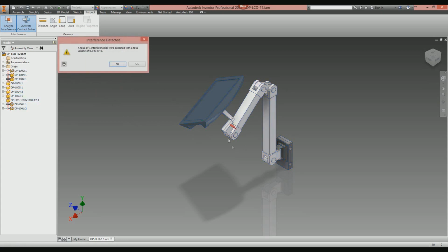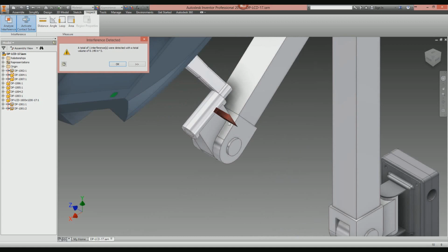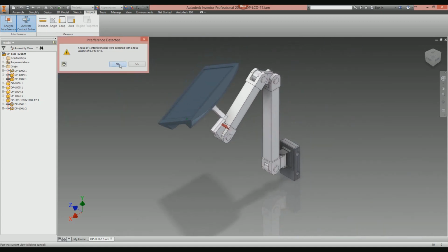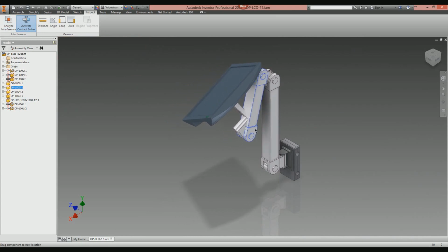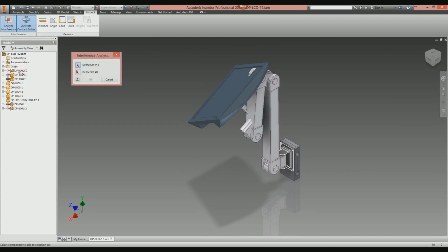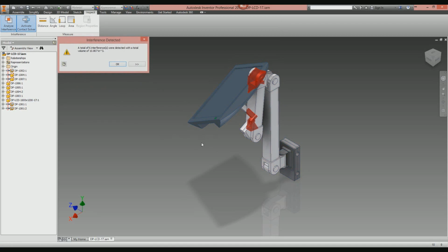And then wherever there's clashing, it just highlights wherever the clash is. It happens to be like a little wedge-shaped clash, but that's where the clashing is. If we select OK, and we just give it a little bit more clashing, there we go. It visibly is obviously clashing, but we now know what to expect. Analyze the interference, select all the pieces, shift and click, press OK. It's now giving us a big red selection where there is clashing going on.